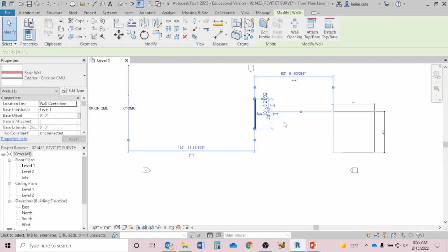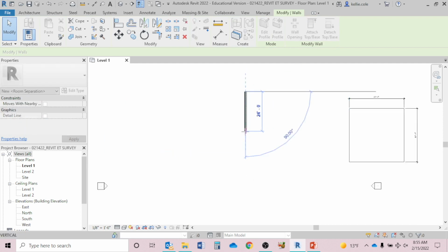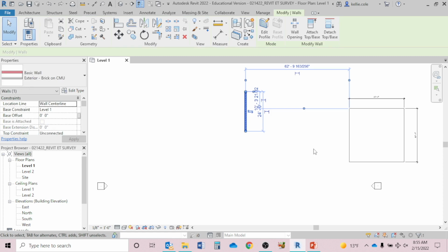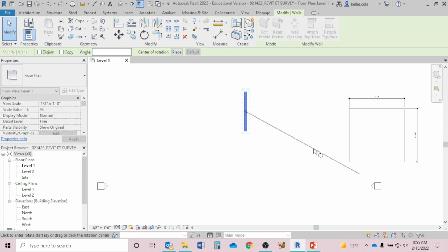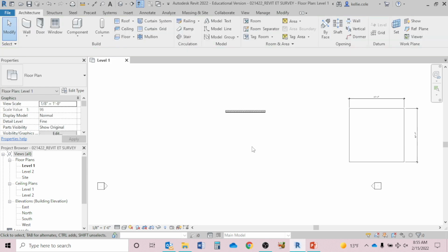We're going to rotate this wall. We can do that 2 ways. We can select it, touch an end grabber and drag it, or Control Z changes it back, or I can select it, type in RO rotate, select anywhere on my drawing, type in 90, enter. Okay. I've given myself a guide here. I have a wall that I'm ready to work with. I'm going to give you one more guiding system to draft, and then we're going to make sure that it doesn't move on our page.